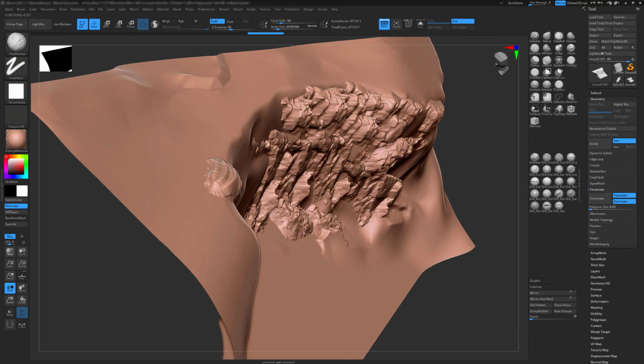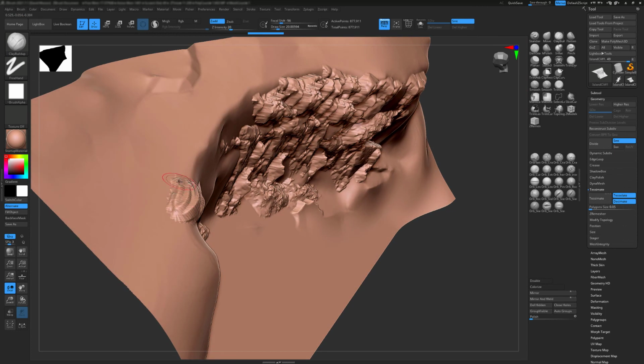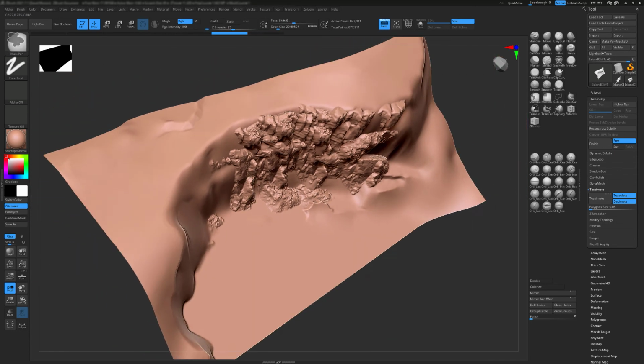In which case, if you then try to optimize it by cutting away some polygons, you may end up with polygons that are raised above the landscape. So when you come to import it back into your level in Unreal, they're floating up in the air, which you can deal with as well, because you can use the sculpting tools inside of Epic's modeling plugin to move them around. But another way to do it in here is to